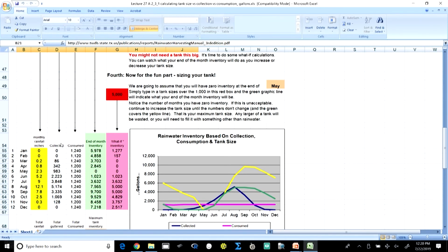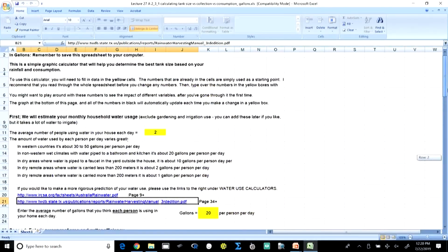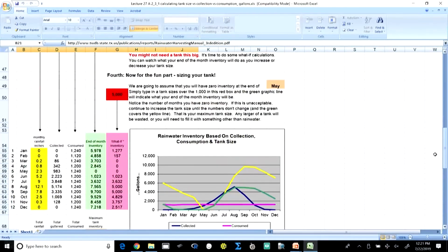On the basis of this, it will give us how much volume is collected based on the total surface area available. We have the surface area given, and we can have the efficiency depending upon the surface, the runoff coefficient. This will give us the amount of rainwater which can be collected in a month for a given place. So, we are not doing it only for the normalized one day rainfall, we are doing it separately for each month, and this becomes quite detailed.